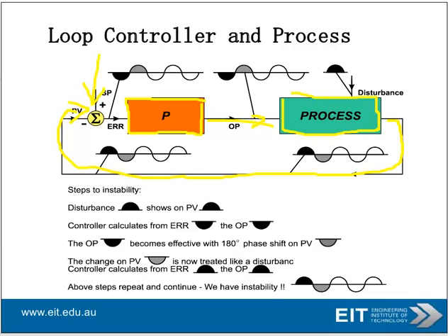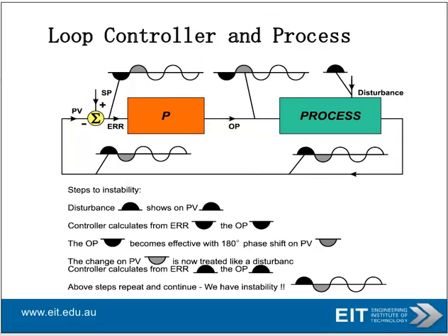You have a set point from the controller, and you get an error developing, which you feed back into your controller. The controller then makes a decision based on that error. And you have three forms of control: P, I, and D. Proportional, integral, and derivative. So the idea is to select them so you get a good response. And the response is based around a few things.